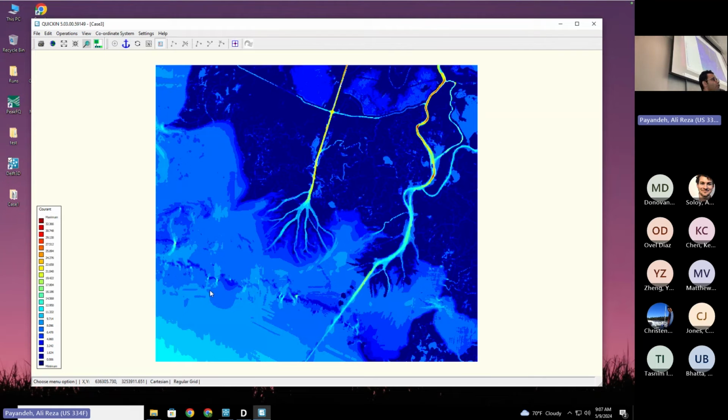You can check the Courant number. It's better, especially on your boundaries, not to have high Courant numbers. Keep it below 1 if you have salinity or sediment in your model, because the advection diffusion equation is going to be solved. And if it's just a flow model, you probably can have a little bit higher Courant numbers. So that's a very useful tool.